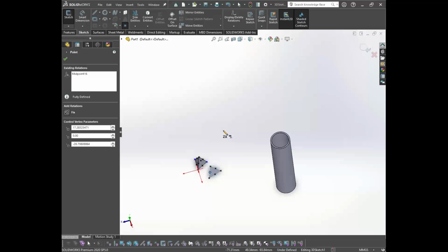So I'll apply a certain factor of safety to it after solving. If I'm getting values close to 150 MPa in the actual FEA analysis, say 150 MPa or 170 MPa or 175 MPa, that is fine. But even if we increase the loading conditions and I'm getting values close to 210, 215 MPa, even though these values are close to the yield strength, there's a chance of failure. So no designer in the world will design a component which will have stress values close to the yield point or a tensile point.